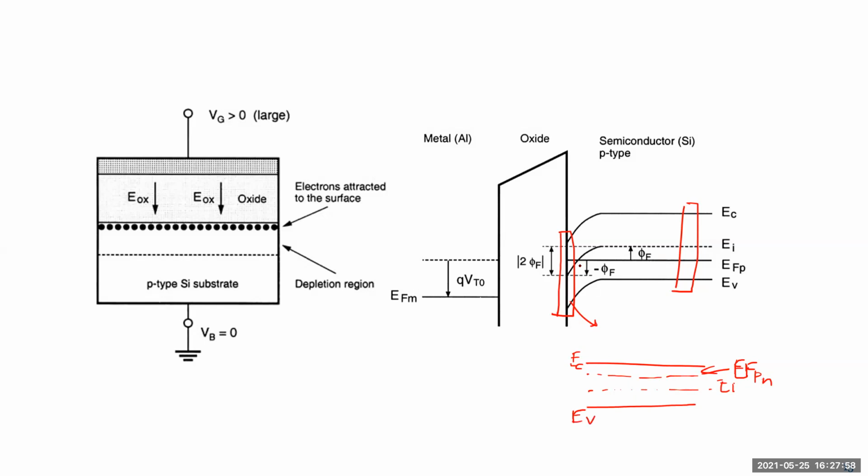And this is your valence band. So if I took a slice of this and did the band diagram like this and showed it to you, this is n-type, right? And it's an n-type of the same magnitude as the p-type, because this φN is the same as whatever you had φF over here. So if you have a certain p-type material and you want to invert the Fermi potential by the same amount, the total potential you want to apply across is 2φF, right? That's the reason why we keep saying 2φF, 2φF.